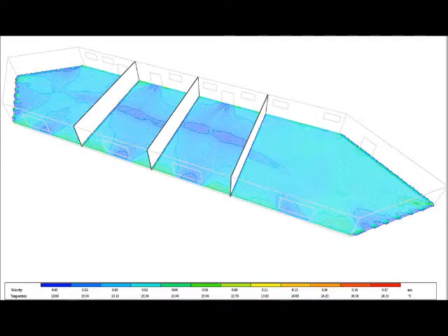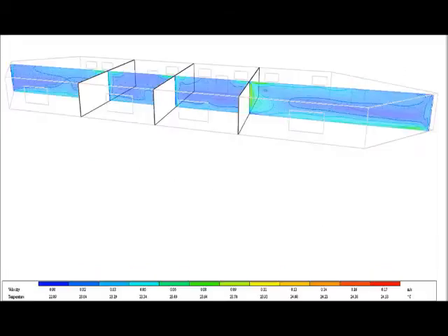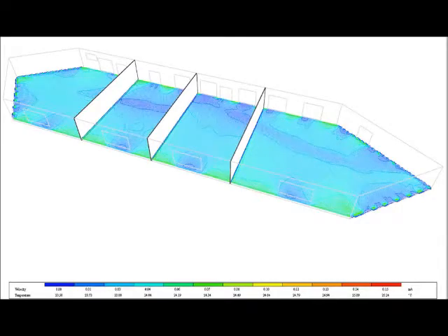second. But when we raised the same windows with the same size to be at 1.9 meter above floor level, as shown in the isometric view, the air distribution is noted to be more unified over the indoor space, and the temperature is reduced to 23.7 degrees Celsius, since the solar gain is reduced due to the small window size. However, the velocity is still at the same range. At the third scenario, we enlarge the window to be 2 meter height and 1.5 meter